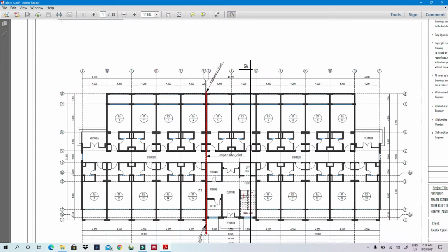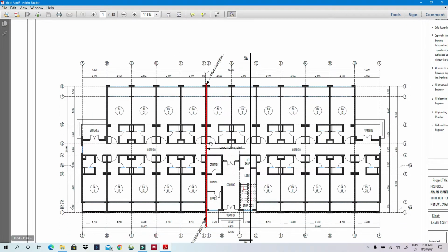So previously we modeled the building, but we were skipping these grid lines, the ones with these ducts, because the architects wanted these ducts to be free. But this would have made our span 8.4 meters, which is very huge. That's why you saw me, when I was defining a beam, use a 600 depth.